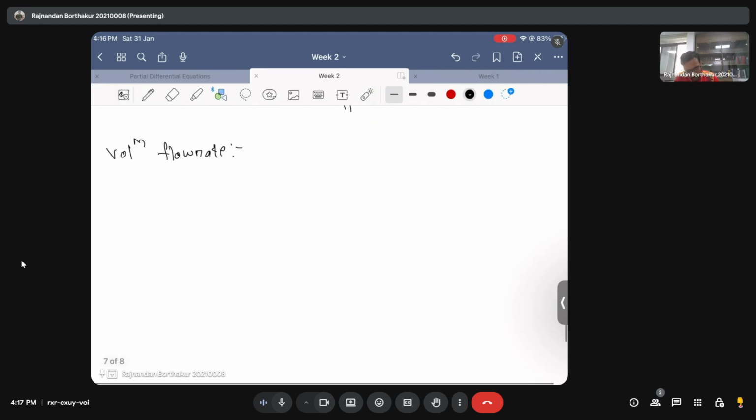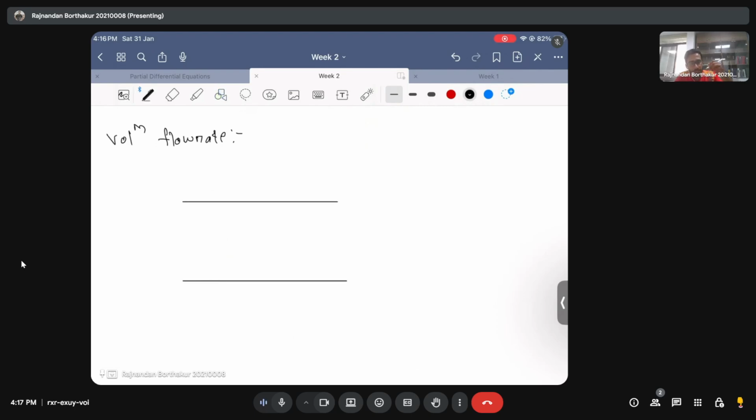For the volume flow rate, this is similar to what we did in the first example that we saw today, and we'll apply the same principle, because we know that my velocity profile is varying along the y direction. This is x and this is y. So I will pick a particular y and choose a small differential area there. Its height is going to be dy, and its width is going to be inside this plane.